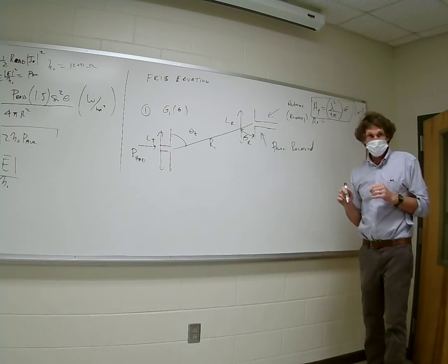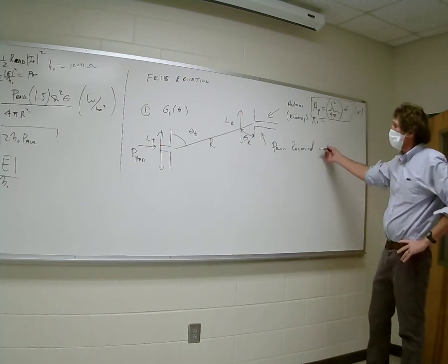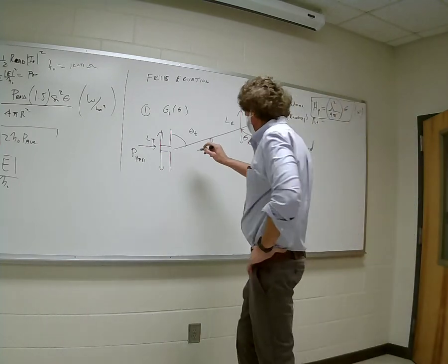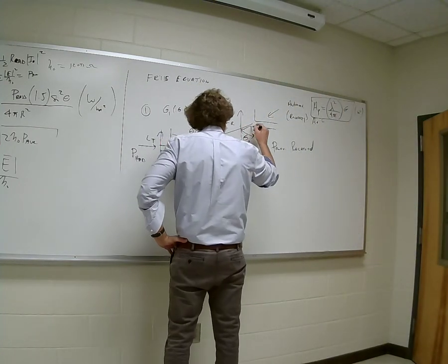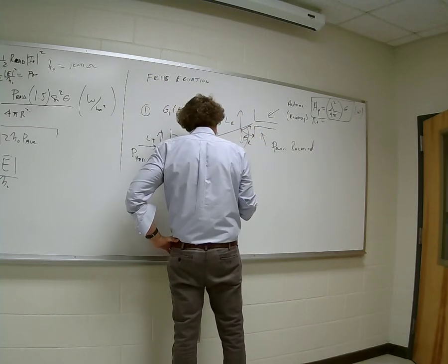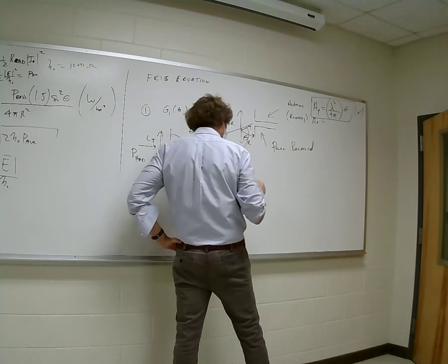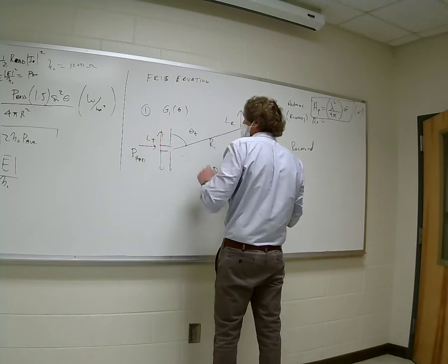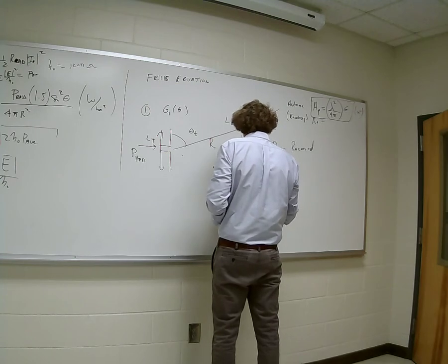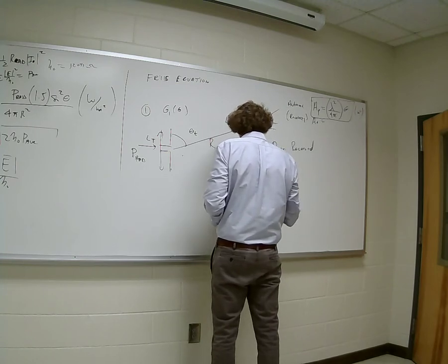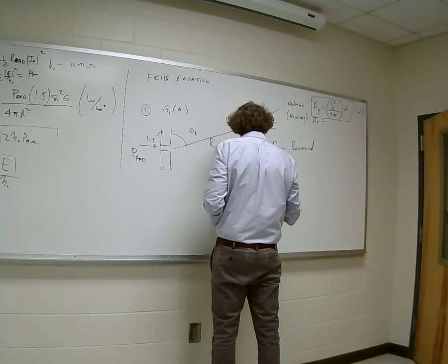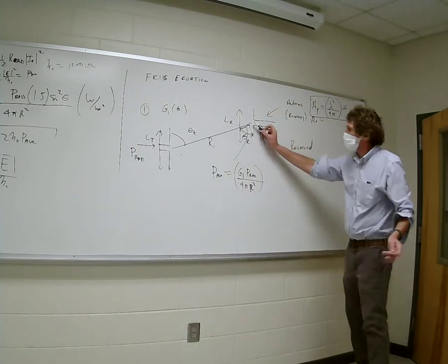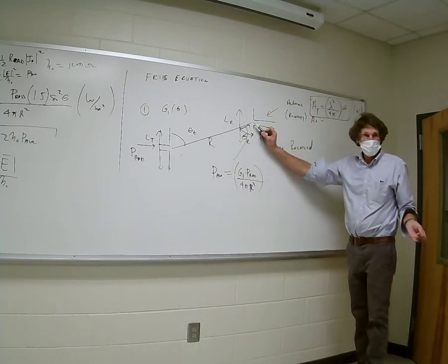This is the beginnings of that, what I'm showing you. It's easy to do. So anyway, when you have this right here, if that's the effective area, follow me on this. I'm going to come down and say, I know the average power density right there from that antenna, P average, we just did this, would be the gain of this antenna, I'm calling it G1, times the power radiated over 4 pi r squared. You all agree that that's the power density from the first antenna right here? Agreed, class?